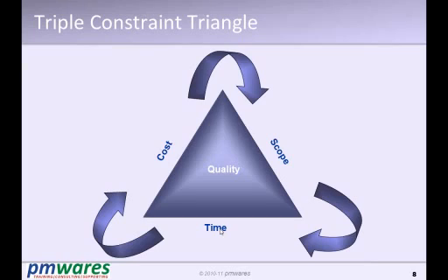You can add resources, you can try compressing the schedule and see whether you are able to meet it or not. So today you can do several kinds of simulation in MS Project and try out various options which you have.